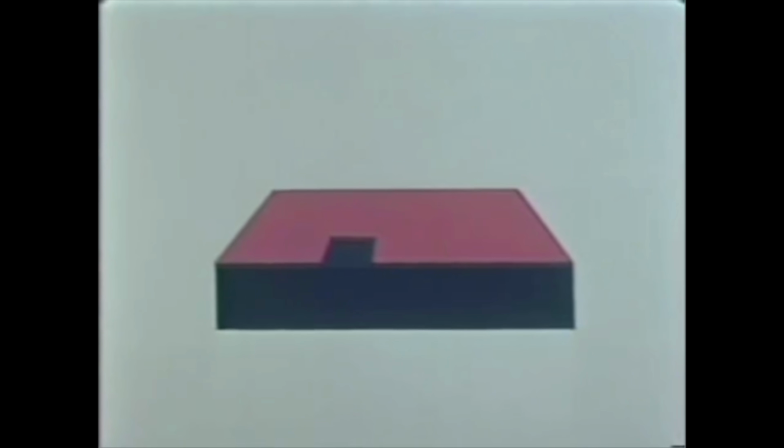In the next operation, called diffusion, the wafer is exposed to a dopant. This impurity diffuses through the window and into the silicon below, forming the collector of a transistor in our integrated circuit. But notice, at the same time diffusion is taking place, more oxide is being formed. This is the essence of the planar process. Now we're going to strip off the passivating layer and grow a new layer of silicon right on top of the diffused wafer by a process called epitaxial growth.